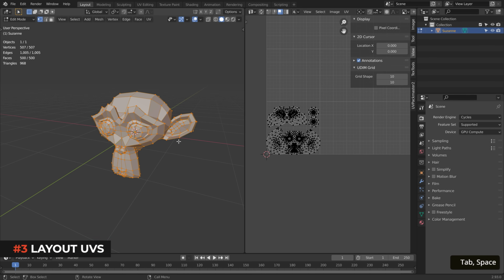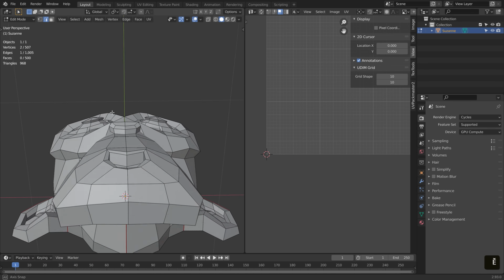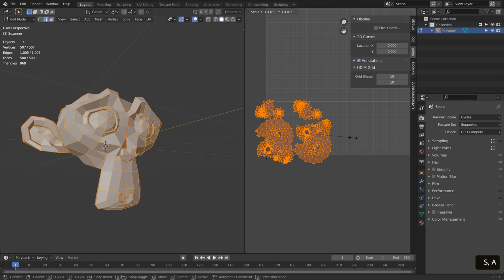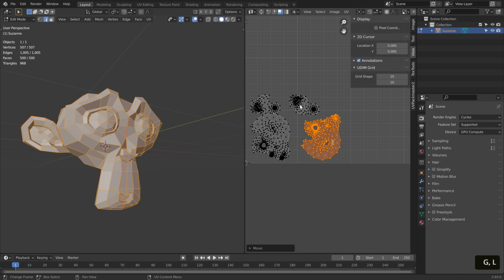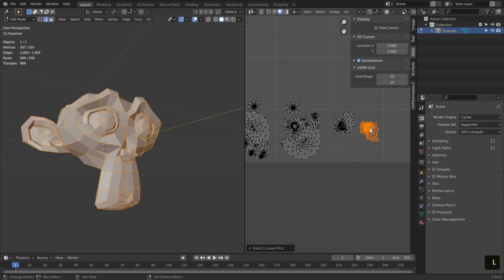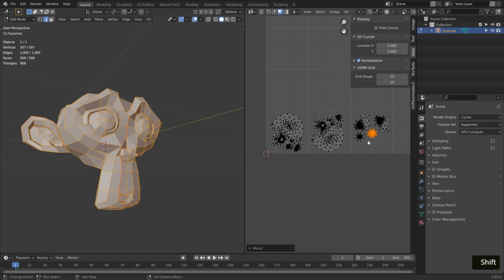Once you have your grid ready, you can start to lay out some UVs however you need. You can do this in the traditional way you are used to preparing UVs, only that now you are not limited to a single tile, but you can use as many of them as you want. The only rule to keep in mind is that UV islands should not go across tile borders, so you should always keep them inside of one tile. Also, even though you can have lots of resolution, you should have an idea of how much you actually need. At the end of the day, UDIMs do cost resources, so you want to keep working in an optimized way.